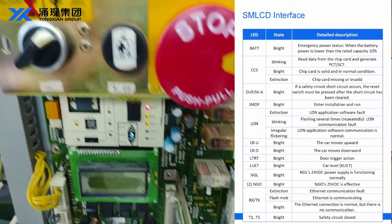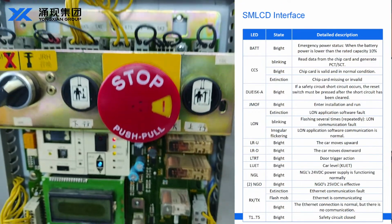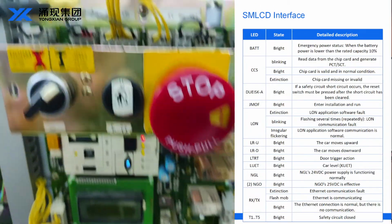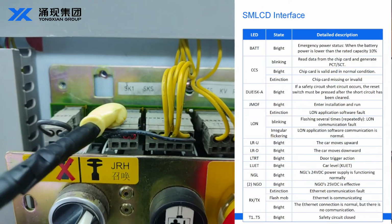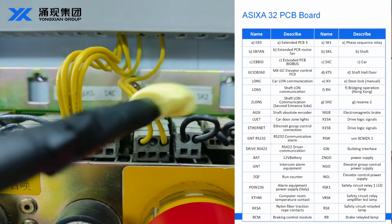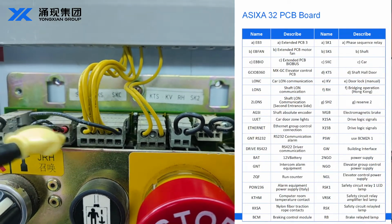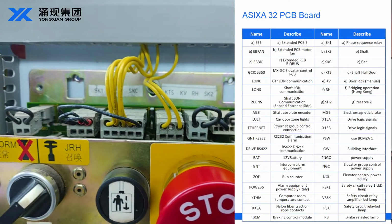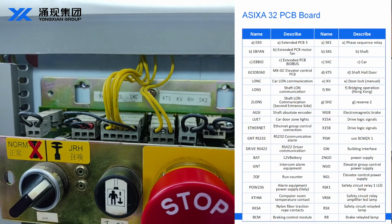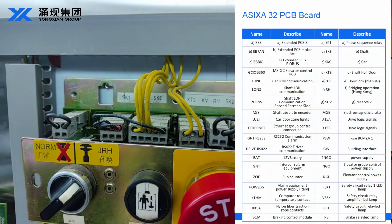Okay, let's continue with the definition of the main board. We start from this part, the XP1 connector, our SKS, SKC, and also our PTS. What is this part for? It is our safety circuit, connected in series from here, including the car door lock and the landing door lock at this position. So as you can see from SK1, SKS, SKC, and KTS, it's a safety circuit. It includes the shaft, the car top, the car cabin door and the landing door also.